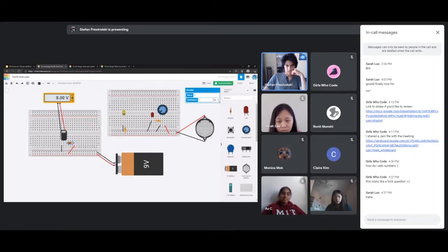Yeah, maybe I think I need more resistance actually. And you can see that the voltage gradually picks up as current is charging the capacitor. And it's gonna start to slow down as it gets to 9 volts, as it charges up to its full 9 volts. Well, it's not even actually gonna reach 9 volts. Let's see. Give it enough time and it probably will. So I input a very high resistance value so you could sort of visualize it.